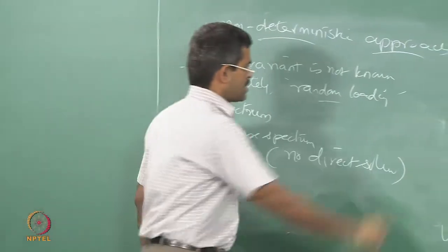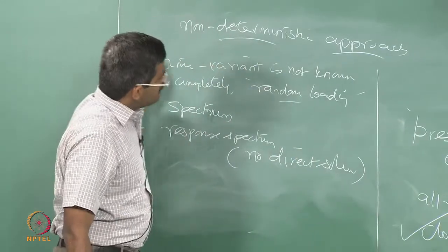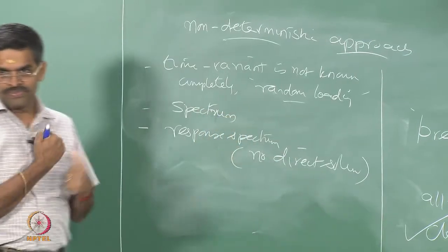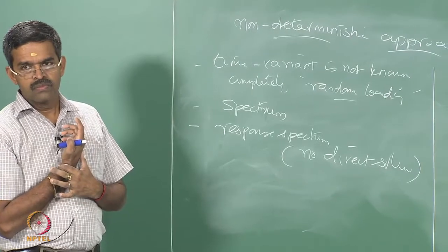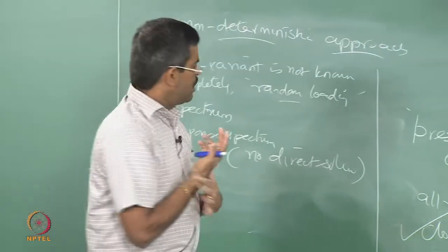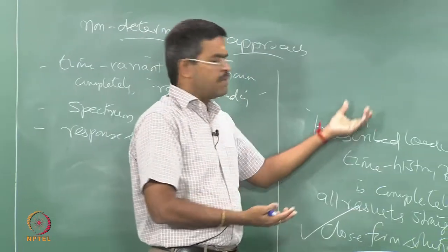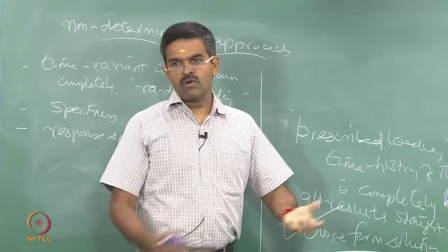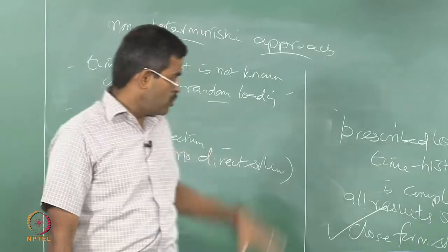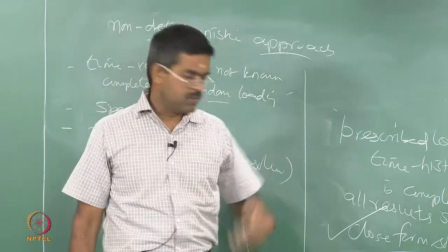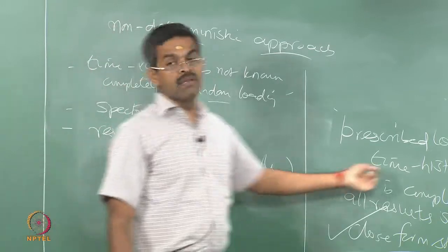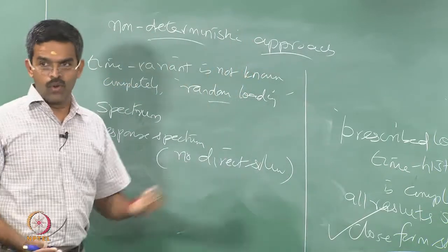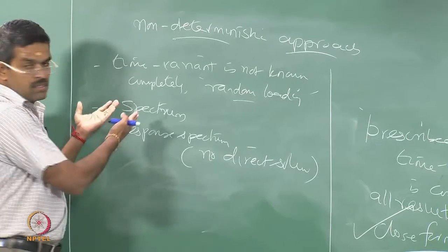Now, again there is a basic question in mind. Sir, amongst the 11 types of loads we have discussed just now, which are prescribed loading and which are non prescribed loading? For example, dead load is a fully prescribed load. Essentially it is not even dynamic in nature, it is more or less time invariant, because dead load is more or less static, except if you do not include the variable submergence effect on the dead load. Live load is more or less time invariant, so it is a prescribed loading. Wave load, wind load, earthquake load are more or less random in nature.